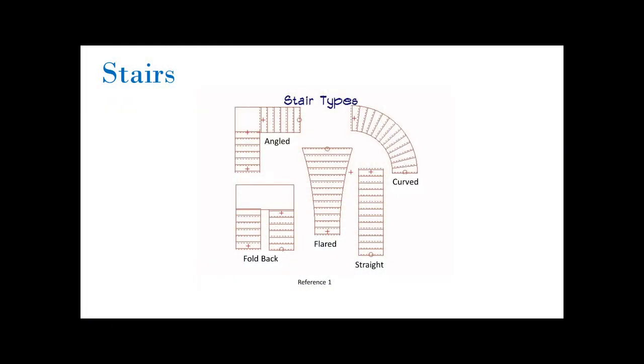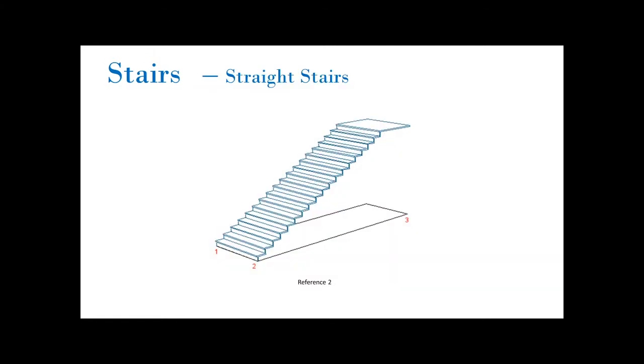There are many different types of stairs. The simplest and most commonly used is a staircase with a straight flight, meaning its elevation gain continues along a straight line. However, these stairs are limited in height because the number of treads, the part of the stairway that is stepped on, along a single straight flight is not allowed to exceed 16.